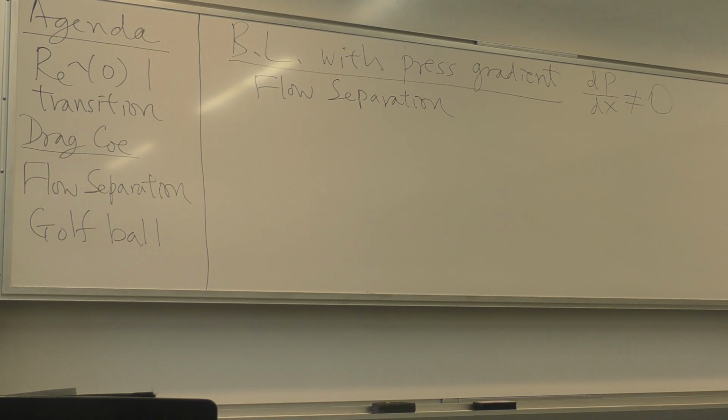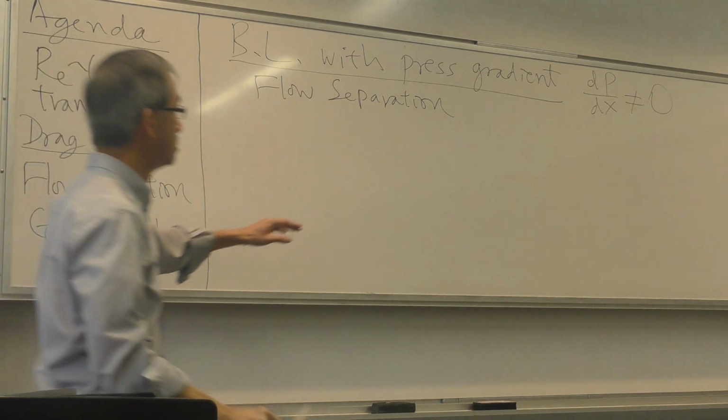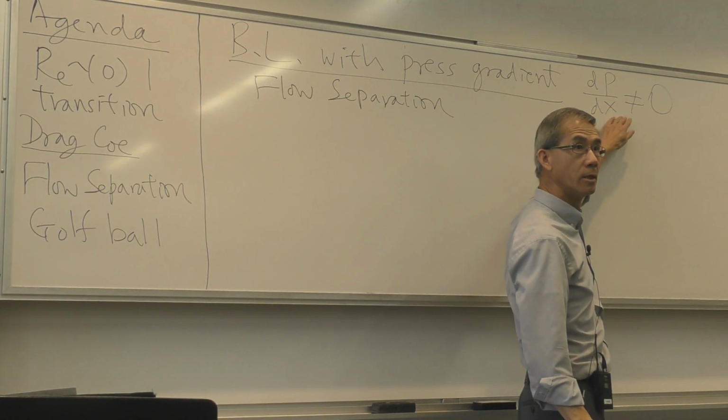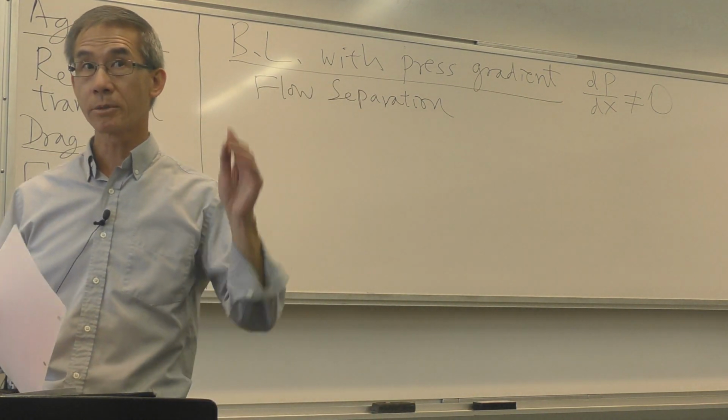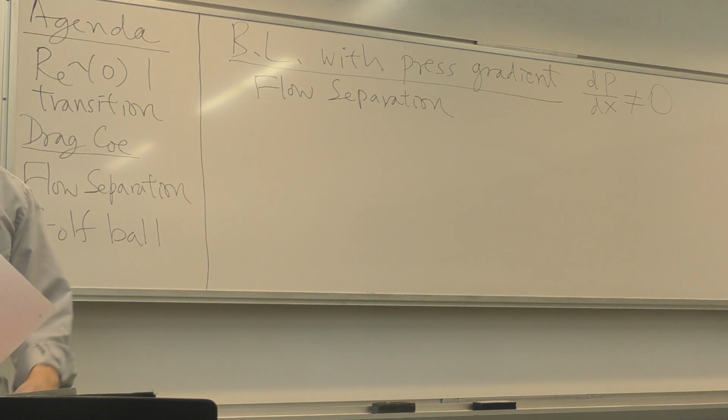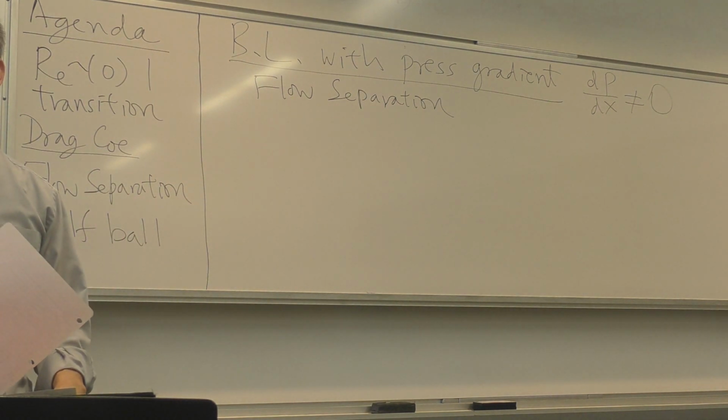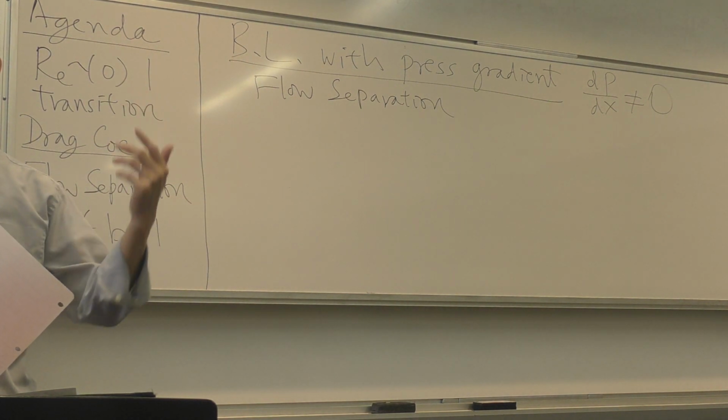On this device, this is not a flat plate. The flow on the pressure and suction side has severe pressure change that led to this discussion. Some of that pressure change is actually beneficial. It helps keep the boundary layer attached. But there are others, which are opposite, that will cause the boundary layer to peel off or separate.